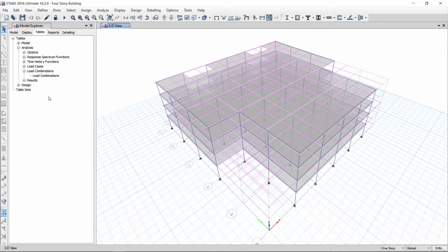Rather, I can say it will be a little bit uneconomical if you are designing for a higher load which is not needed. And the logic is, in case of an earthquake, this structure will not be fully loaded with the design live load. So they should think logically.